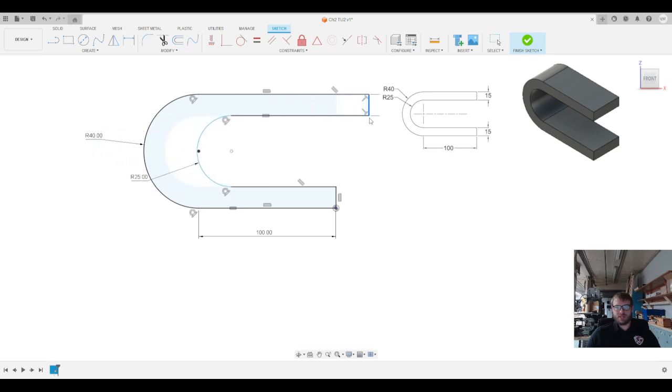Okay, so what happened? Well, that can change. So there's two ways I could fix this one. I could make this line collinear with that line. I could make this length be equal, because if this moves, then that changes. Or I could make these points sit on top of each other. And if I just drag it to there, it will do that. But I'll hit undo just to show you the other options. I could select that and then hit coincident and select that one. That would do it. Or if I hit undo, I could make that one collinear with this one.